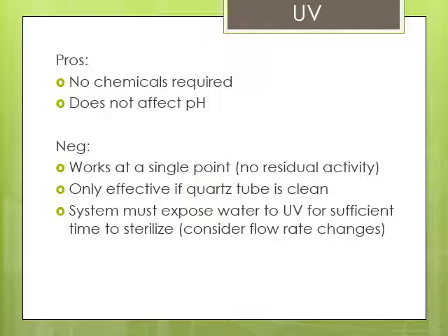There's no chemicals, which also means there's no residual. You only have contact when the UV light is shining on the water. Once the water exits that tube, there's no more biocidal activity. So all the biocidal action happens while the water's in that short tube. So your flow rate is really, really critical. You need sufficient contact time to sterilize. So that's a really important one for UV light.